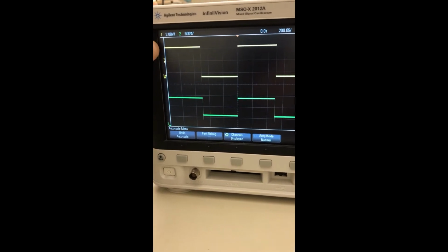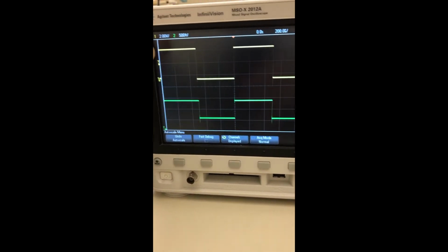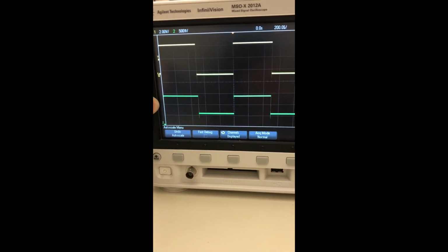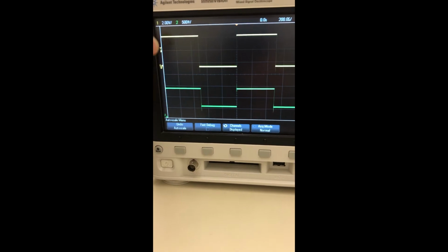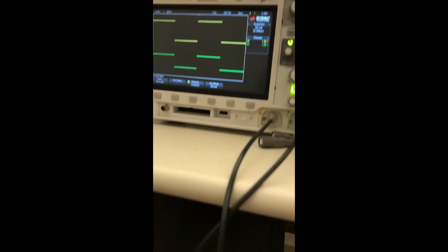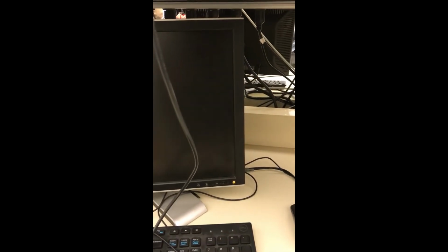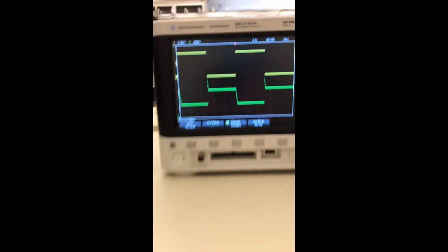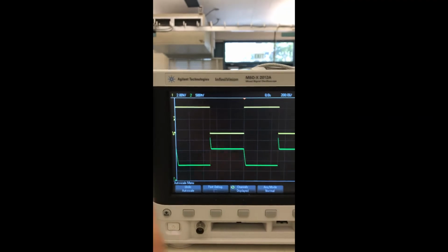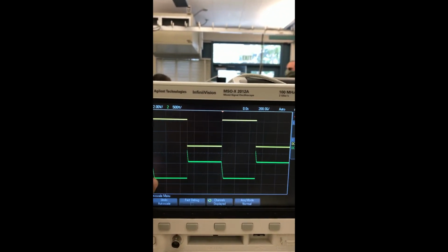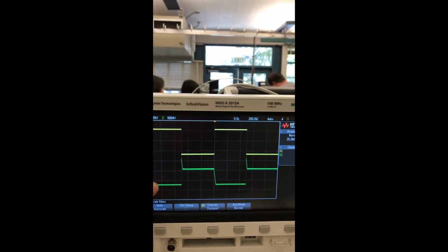It can be seen that our input to the TTL is inverted, and then inverted again by the ECL, so it can be seen as kind of a buffer. If we switch our channel 2 scope to the OR output, it can be seen that our input is inverted and then buffered by our ECL, and so it represents the inverted version of our input.